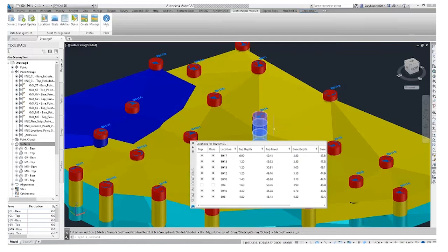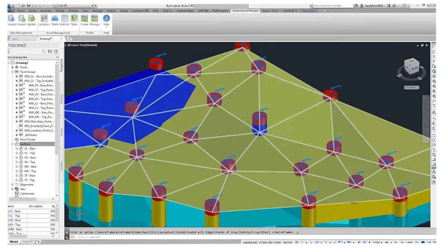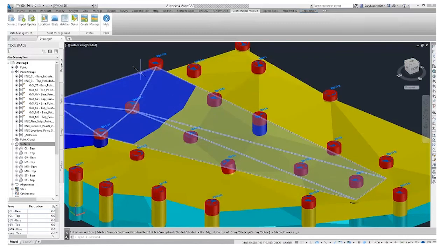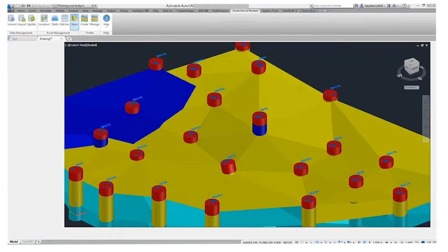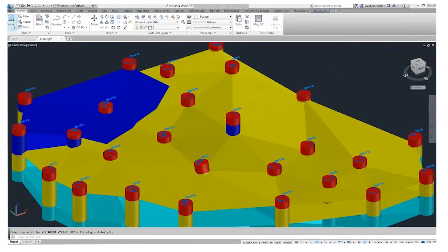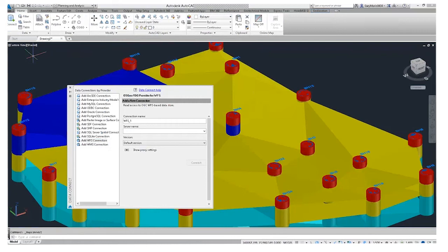Now, in reality, this is just your starting point of getting the data in. You need to refer to geology maps, look at WMS mapping services, photographs, a whole host of different data sets, and AutoCAD Civil is a great place to do it. One thing that people quite often forget is that AutoCAD Civil, if you go down to your Planning and Analysis section, has in it all of the AutoCAD Map functionality. So look at all these GIS formats we can load in.